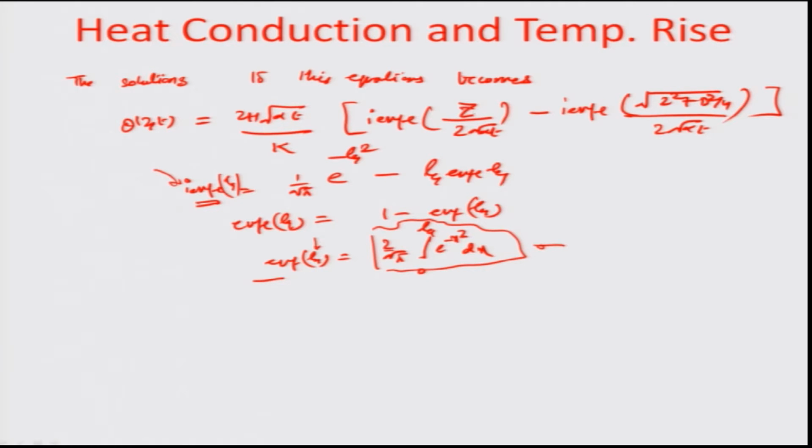The zeta in one of the cases is z, the depth of the melting temperature, divided by root of twice alpha t. Alpha is again the thermal diffusivity, which we calculated in one of the last steps as K by rho C, the conductivity per unit volume specific heat, and t really is the time up to which you have to wait until theta for a circular spot comes to the melting point of the material which is being hit by the laser.